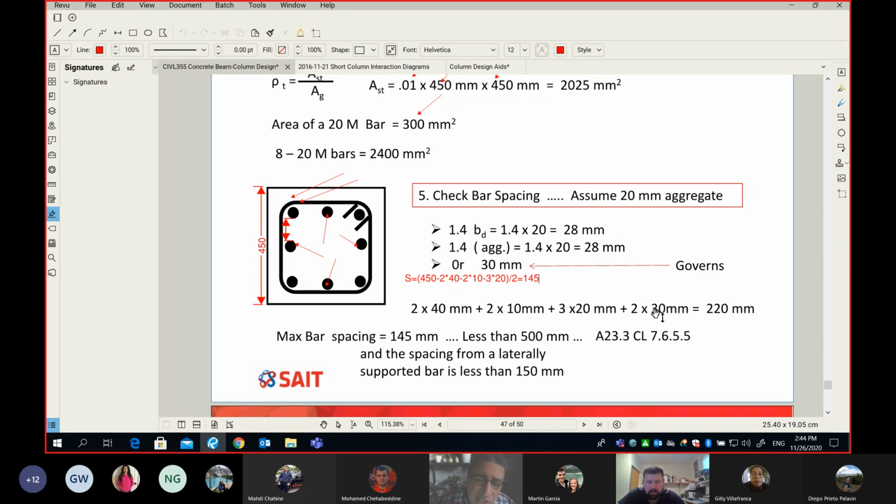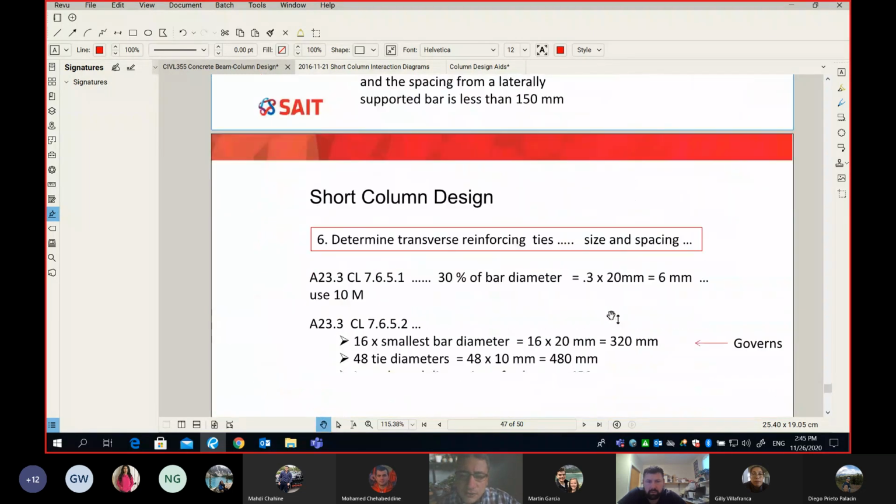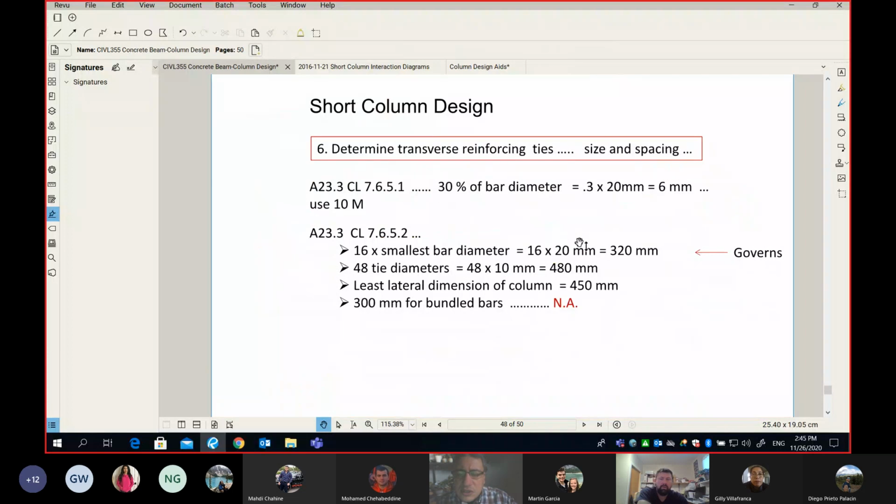If this distance that I just mentioned or estimated a minute ago exceeds 150 mm, in this case, let's say 155, or maybe 160, then you need to provide more support for these bars, which will have to add this diamond tie. Now we know the shape of the tie.